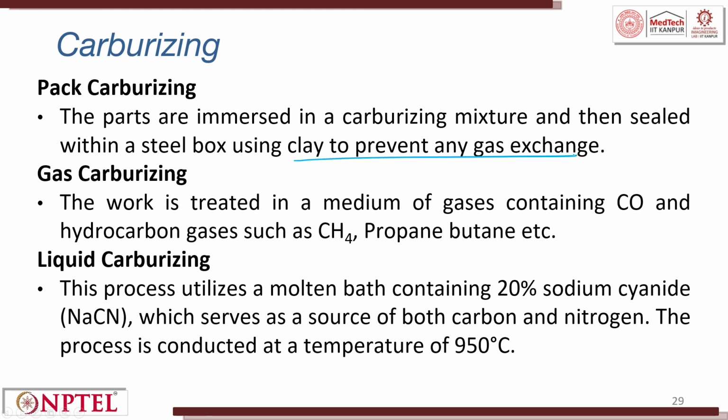In gas carburizing, the work is treated in a medium of gas containing CO and hydrocarbon gas such as methane, propane, butane, etc. Liquid carburizing uses a molten bath containing 20% sodium cyanide, which serves as a source of both carbon and nitrogen. The heat treatment is done up to 950 degrees Celsius and then you do carburizing.